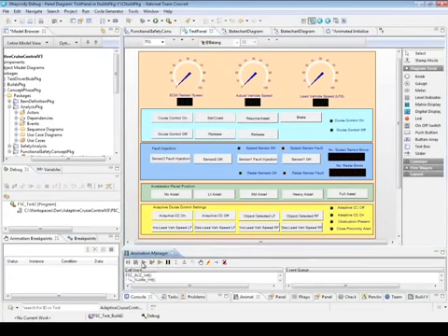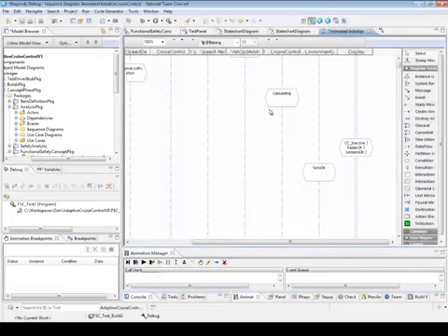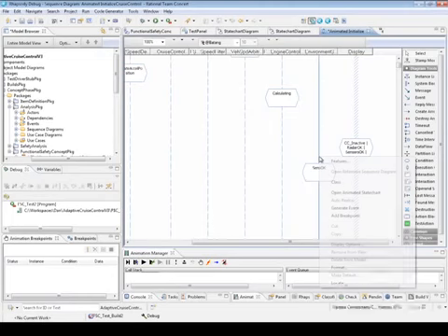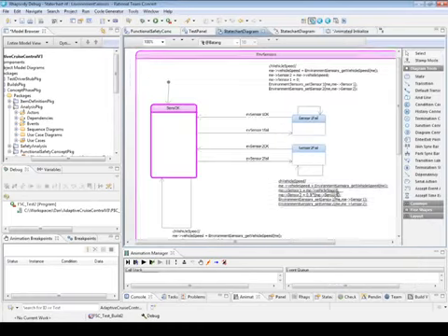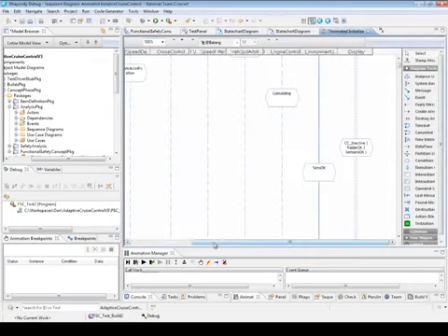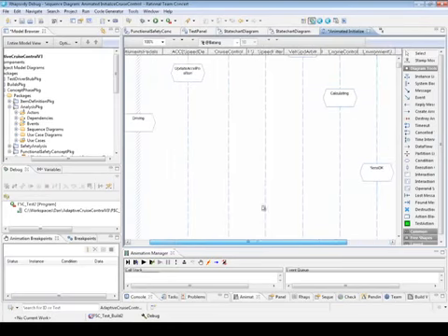And we have just started the simulation. It's now been initiated with the cruise control off, radar sensors are OK. We can start to look at states within the model. In this case, the environment sensors. The sensor is okay at the moment, and we can put it in one of two fail states. First one is used to simulate when the sensor signal is not there. The second is when the vehicle speeds are different. It generates a sensor speed which is different from the first sensor speed. The other information that we're interested in is we're going to look at the cruise control.